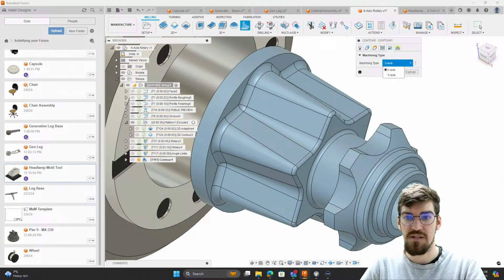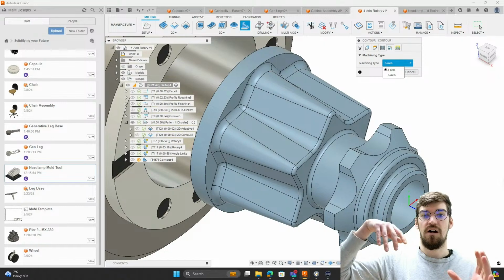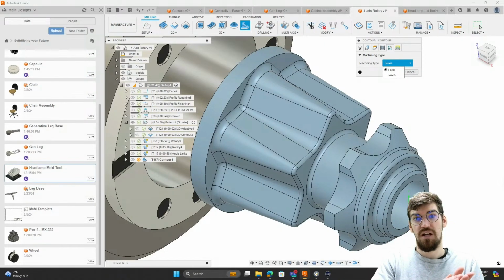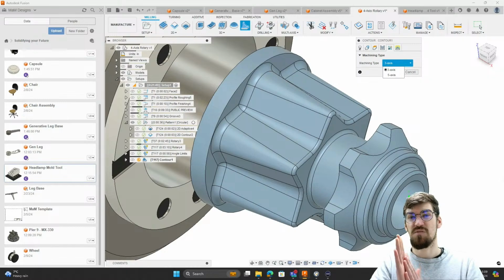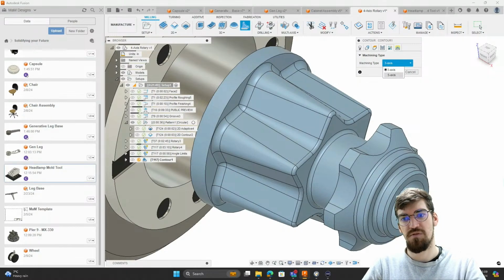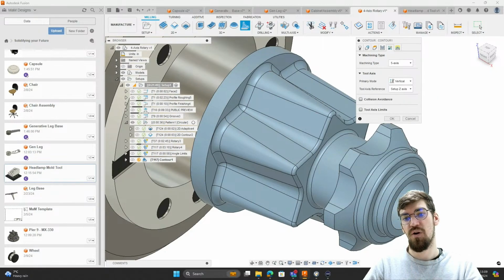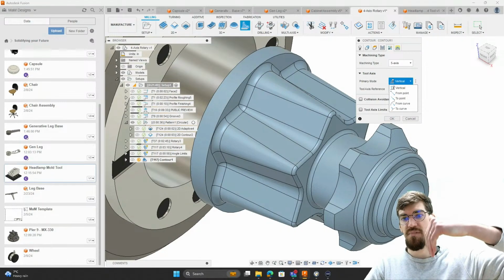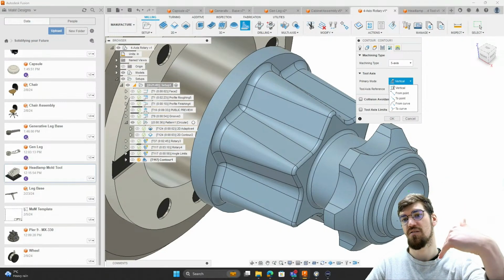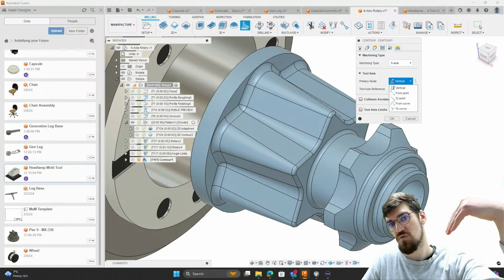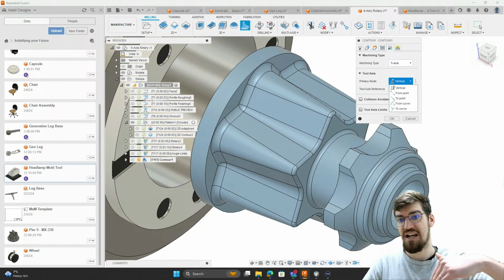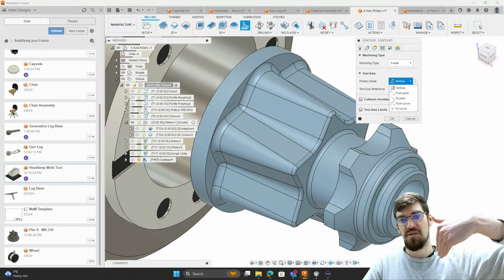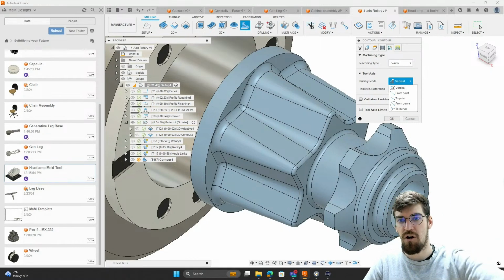but we can also use the same strategy, allowing us to treat any sharp edges or any steep surfaces, and then tilt our tool just to avoid any collisions with any other geometry. So we've got the ability to set a primary tool axis direction, and we can either say that it always needs to remain vertical, or we want to come in at a bit of an angle, either directing the tool always to a particular point or particular line, or from a particular point and from a particular line if we wanted to machine inside of any pockets in that.